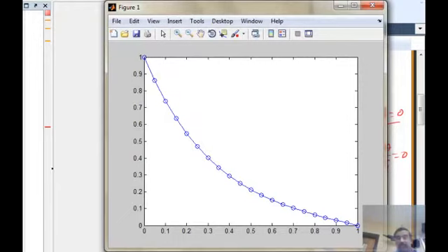This is a problem that you have encountered, and some of you have creatively solved it in your current assignment. For example, I ask you to do it for two areas. One way is to change the area once, run it, and then change the area again, run it. But you don't get both results in the same run. So I want to get all the plots in the same run. How do I do that? You are learning how to improve on the MATLAB function that we have. I'm going to show you the difference between local and global variables that we talked about earlier, and how I can use that to change the value of H inside that function from outside.